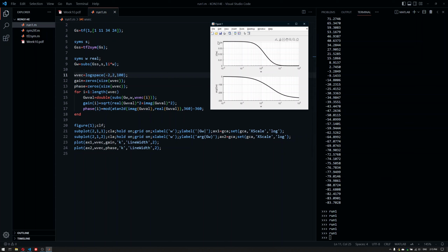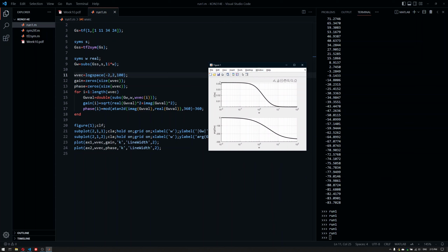You can see that this is not decibels. You can just take 20 log 10 and then plot gain. Then you will get the proper Bode plot result here. Before I go on with that, I can see that there's a certain gain, 0.04, and then it drops down to 0. So this kind of rejects all the signals when you apply a sine wave to it.